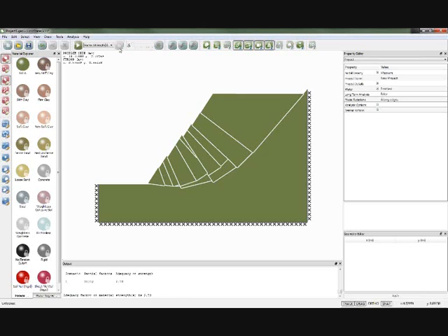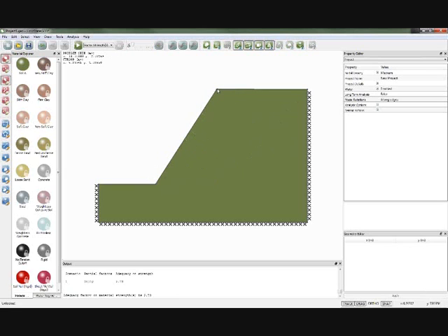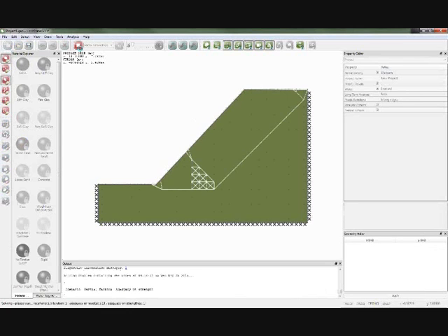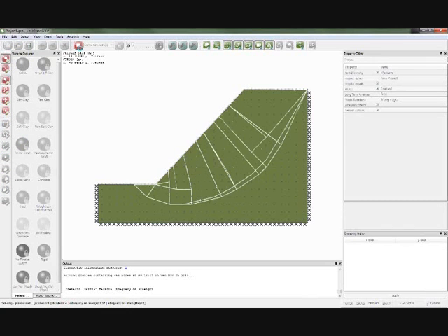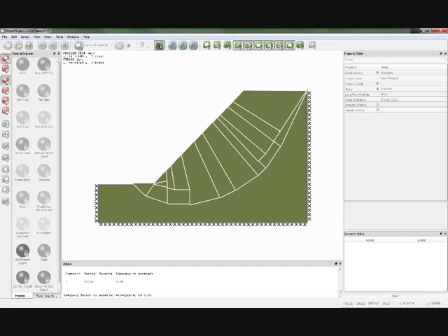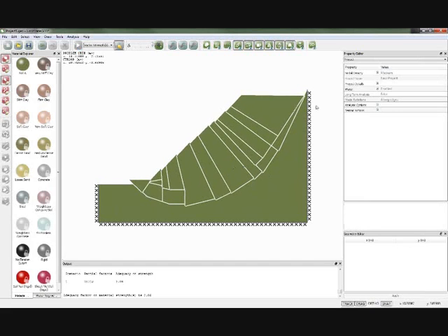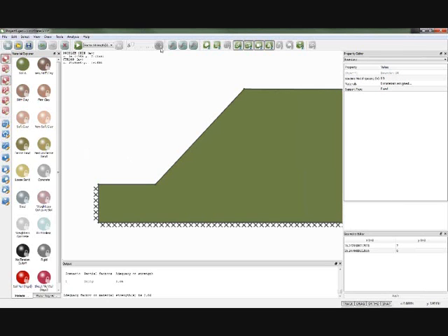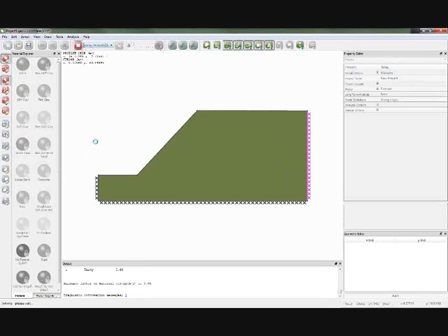So the factor of safety on strength is higher, as we'd expect for a shallow slope. And if I move that back further, I'll start to get a mechanism which goes below the toe. And again, the adequacy on strength, or factor on strength, will go up. In this case, it looks like it's coming out at 3.06. You'll see that the mechanism actually intersects a boundary here, so technically that's not valid if there is really soil behind. And it's very easy to click on the boundary and move it out and resolve.